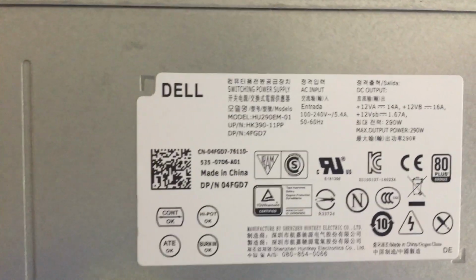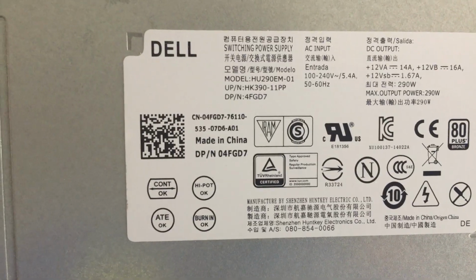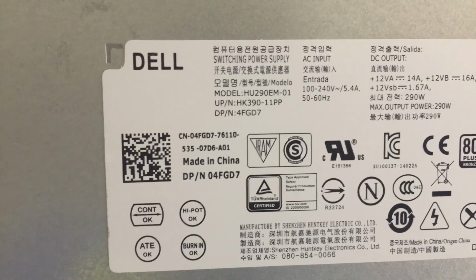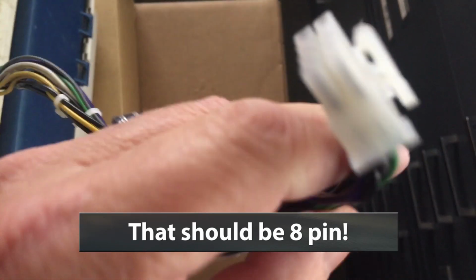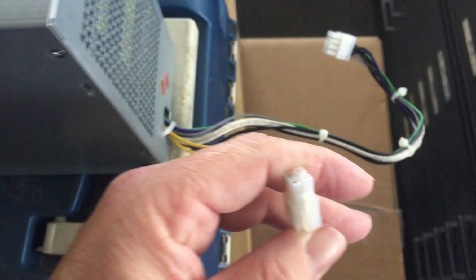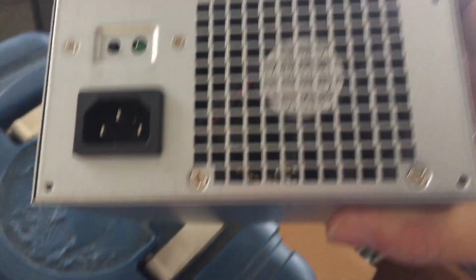Yay! So here's the replacement power supply, and it's Dell part number 04FGD7, and it has a 4-pin and a 6-pin connector, and that's it. That's all there is, because all the other peripherals get their power off the board. So why Dell decided to do this on their Model T1700, I don't know. And it makes the power supply hard to find. And there's a lot of people out there that cheat on these power supplies. It's even hard to get from Dell.